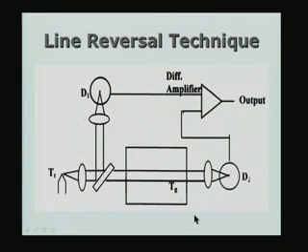A way of doing this measurement is shown schematically here. I have the hot target, in this case I call it T subscript T, it is actually Ts in what I explained on the board. I collect the light coming from the target and I make two beams out of it by having a plate tilted at 45 degrees. One beam is reflected in this direction, the other beam passes straight through. This one beam is made to pass through the gas contained in a vessel. Obviously, there must be windows transparent to radiation at this side and this side, and the reflected radiation is collected directly by the detector D1.